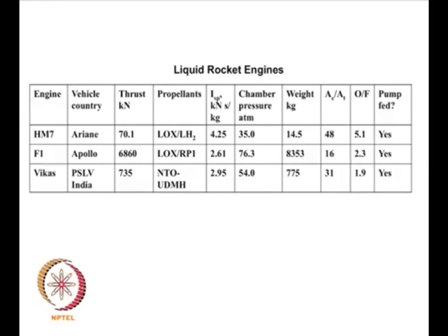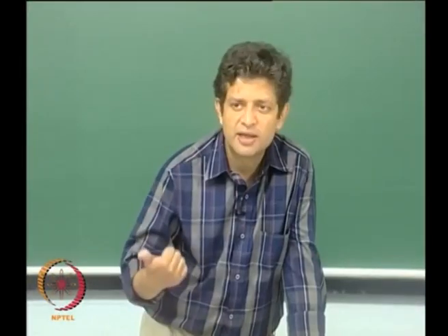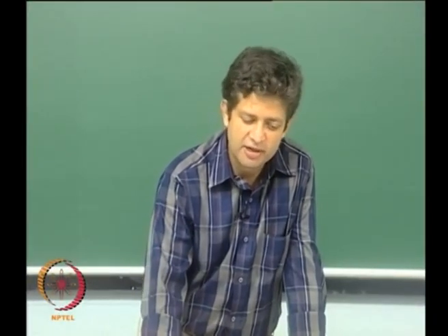If you look at the power of the pump and the efficiencies, the actual achieved efficiency is somewhere around 44%, and it goes up to something like 60% for the pumps, whereas for the turbine it goes all the way up to 80%. Okay. So which means that even though you spend a lot of propellants for turning the turbine, all of it is not obtained as useful work to run the pump. Okay. Only a fraction of it is.